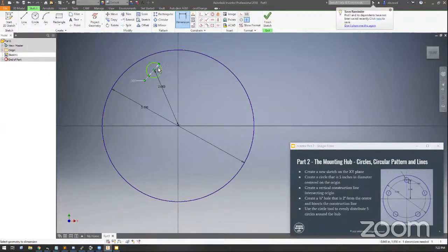So now I actually have this positioned where I want and constrained around the origin circle of the bigger circle. Okay, so I can grab this and move this, and it's always going to be 2 inches from the center. I want to make this so that it's more constrained though. I want to kind of lock this into position.